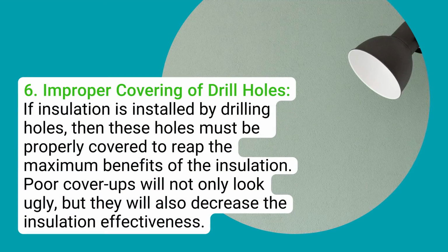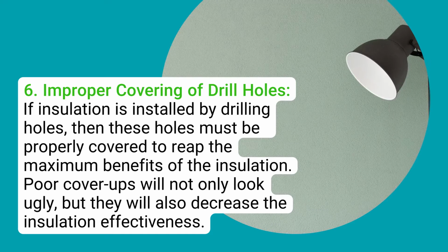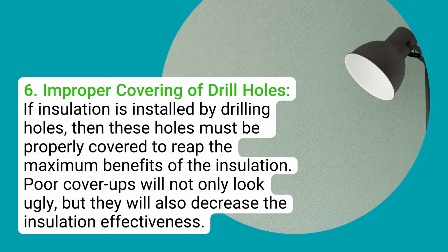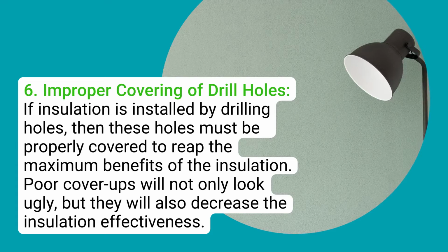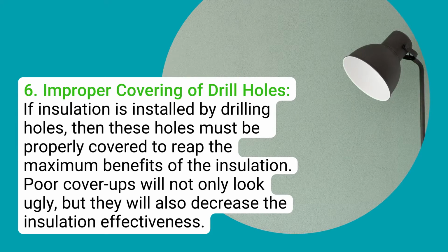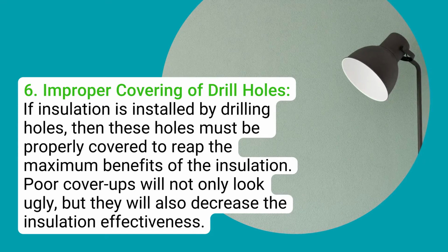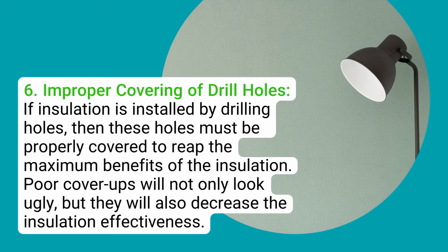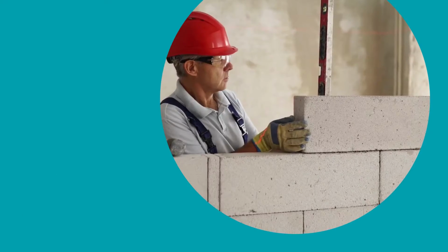6. Improper covering of drill holes. If insulation is installed by drilling holes, then these holes must be properly covered to reap the maximum benefits of the insulation. Poor cover-ups will not only look ugly, but they will also decrease the insulation effectiveness.